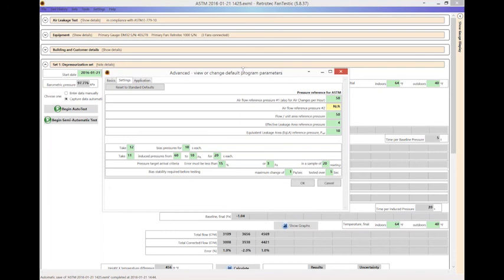Obviously, with small fans, it's not a problem, but often when you're doing a multi-fan test, particularly in the US at 120 volts, there is a good chance you're going to pop the breaker. So you want to get that point established first. Once you achieve your highest test pressure, then there is less heating involved on the breaker, and much less chance that you're going to pop it mid-test and destroy your test.